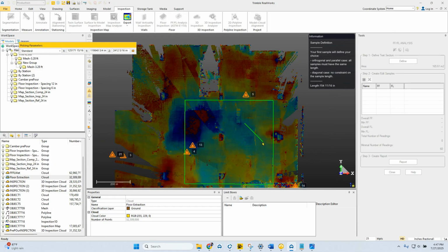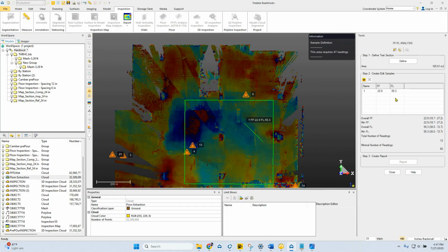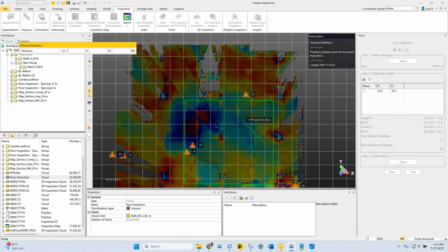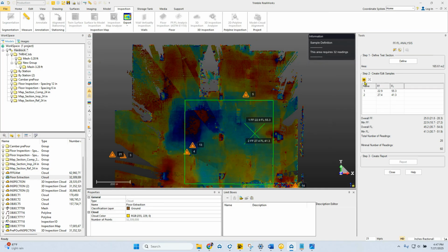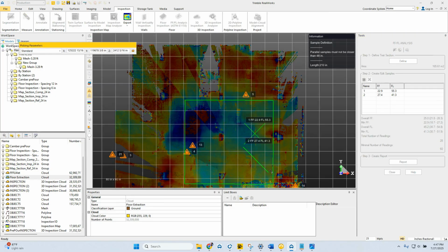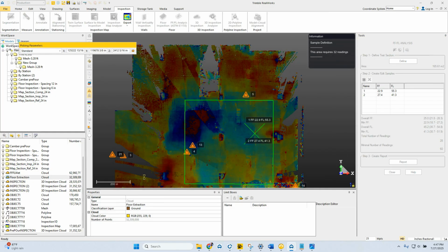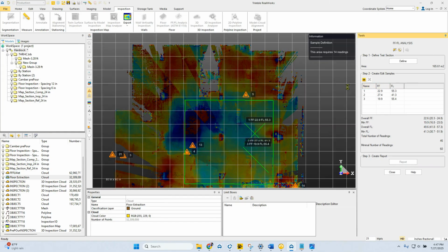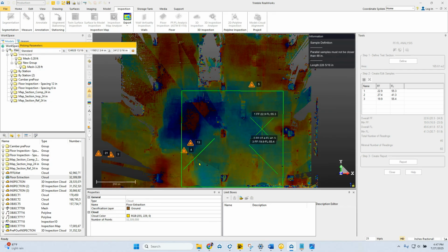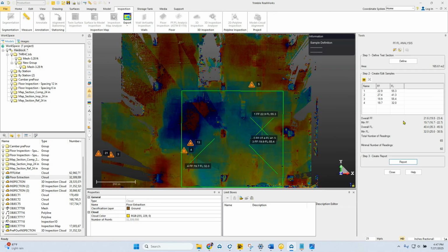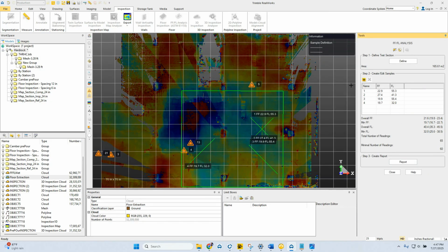But I can start to draw lines for my FFFL. Because this is before any bump cut or troweling, I'd kind of ignore the FF, but I want to make sure the FL is going well. And as you can see with some of these high spots, it's going to be difficult to hit good FFFLs, just because it's going to throw that off. So you can see we're already bringing this down lower.